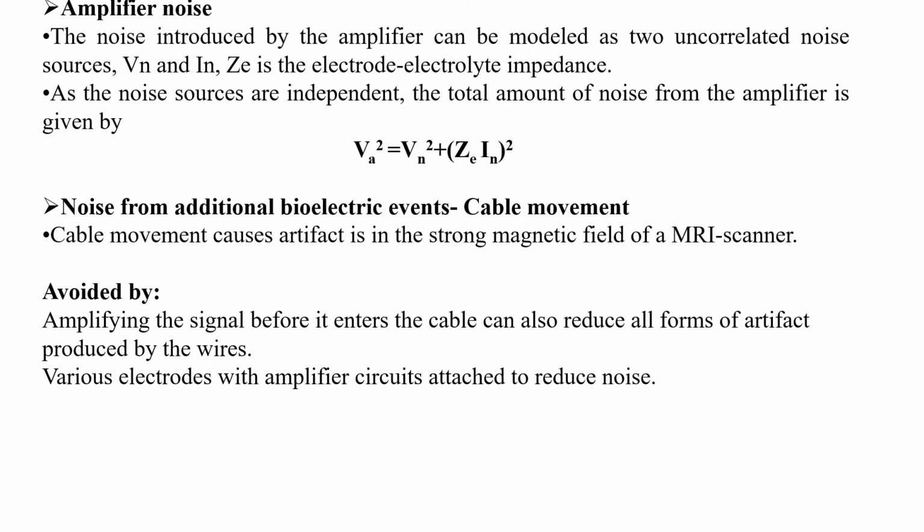For example, why are we using an amplifier? The output of an electronic temperature sensor, which we can take as an example, is probably in the millivolt range. So it is too small for the ADC, the analog to digital converter, to process directly. In such a case, we need to bring the voltage level up to that required by the ADC. This is the way we use an amplifier in biomedical instrumentation during measurement or recording.